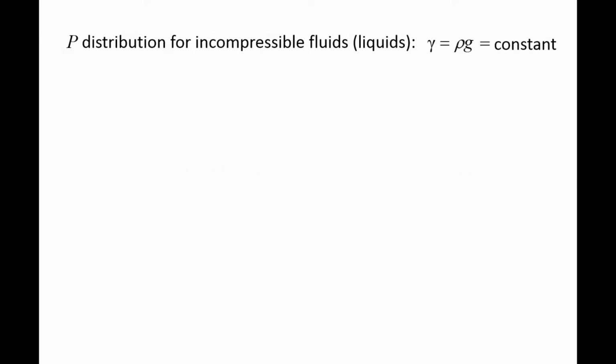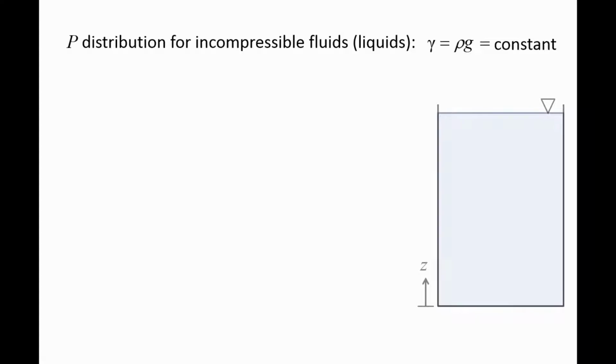In this lesson, we will derive equations for the hydrostatic pressure distribution. A common assumption for liquids is that they are incompressible. That is, their density and specific gravity do not change significantly throughout the region of interest, and those quantities are assumed to be constant. Here is a tank of static liquid. Points 1 and 2 in the liquid are separated by a distance h.